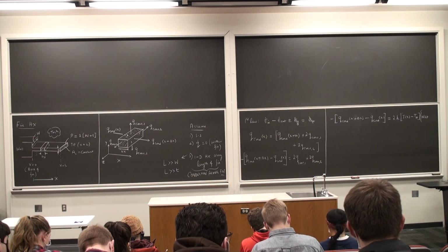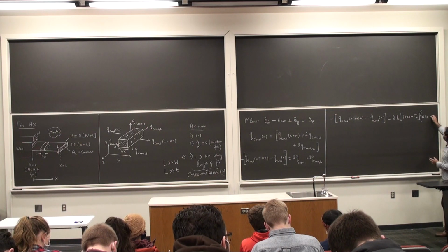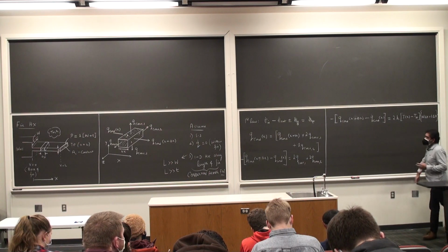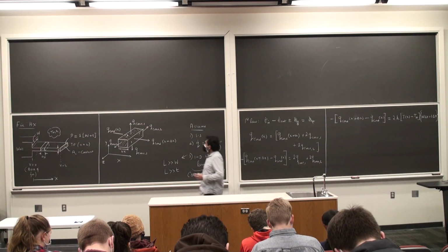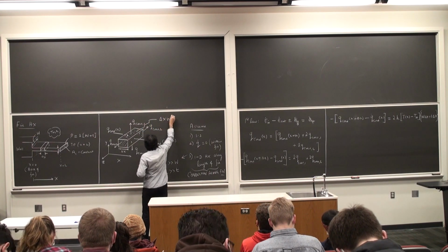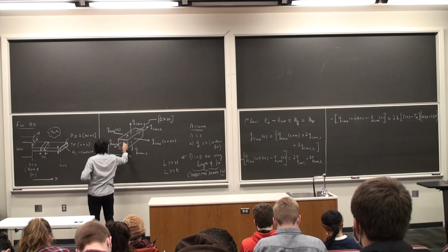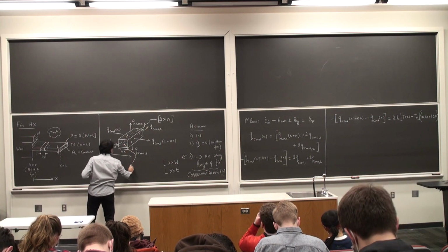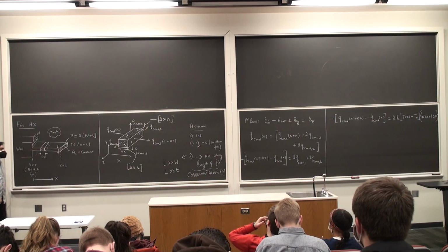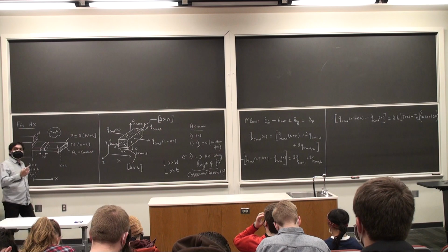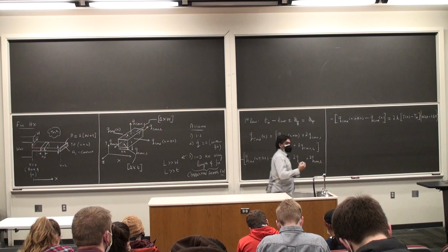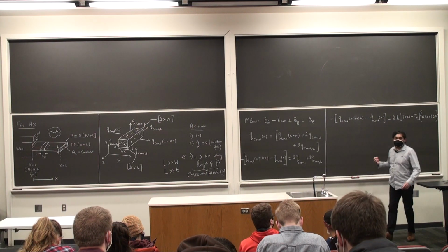And then the side areas, which is the thickness times delta x. So this area here is delta x times W, and this area here is delta x times T. Obviously that factor of 2 and delta x is a common factor. You rearrange everything, you see that you will obtain the perimeter. I'm going to do that in the next step.